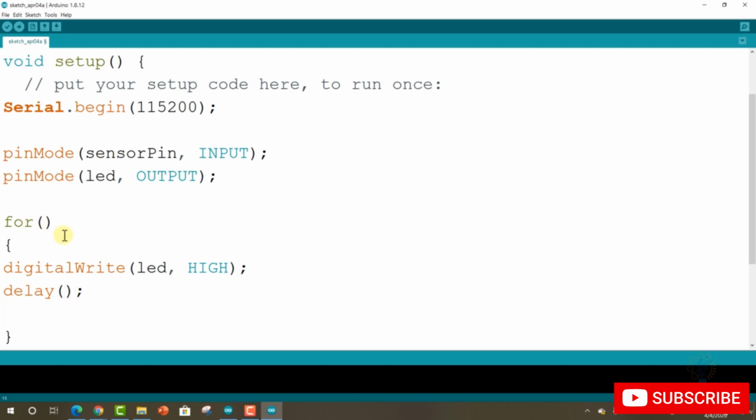We will mention that in a minute. Now let's use digital write again. And inside this digital write, we have to use LED again, low. As you can see, high will turn on the LED, low will turn it off, and we will also need to add a delay.